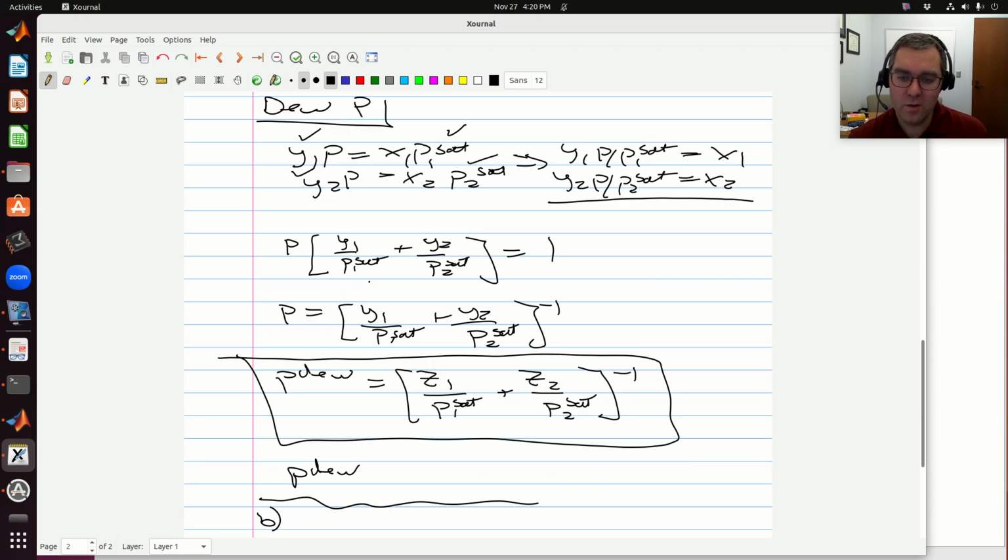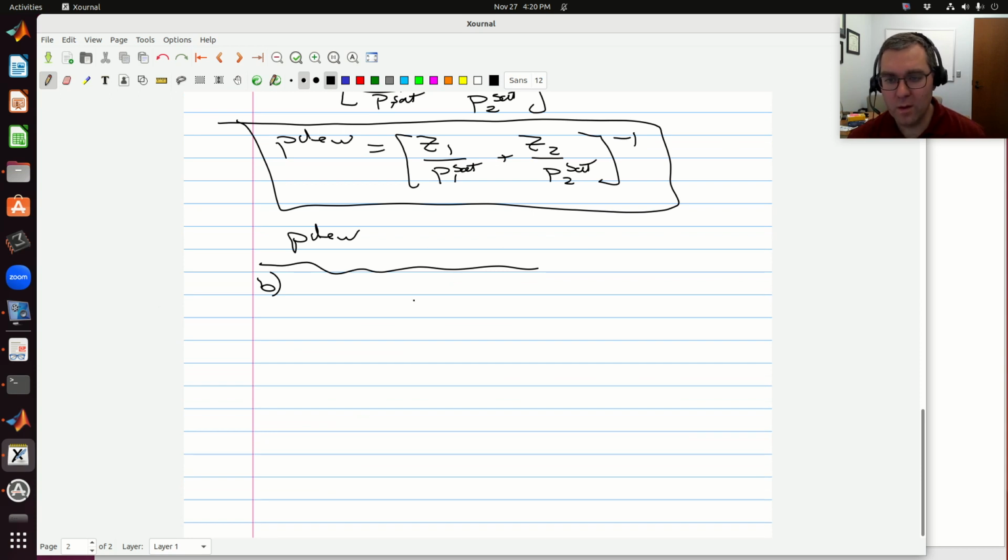Okay, so when I do that, I have y1 p is equal to x1 times p1 sat. And for completeness, we have y1 times p bub is equal to z1 times p1 sat.